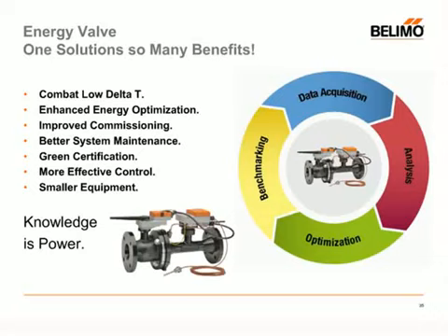A very powerful concept. And then last but not least, this smaller equipment, I like to think of this as it basically rehabilitates your chiller plant. Instead of being on the verge of not having enough capacity, you are releasing capacity that you've paid for, you've never actually been able to get your hands on, because this low delta T syndrome is not allowing the chillers to run properly.